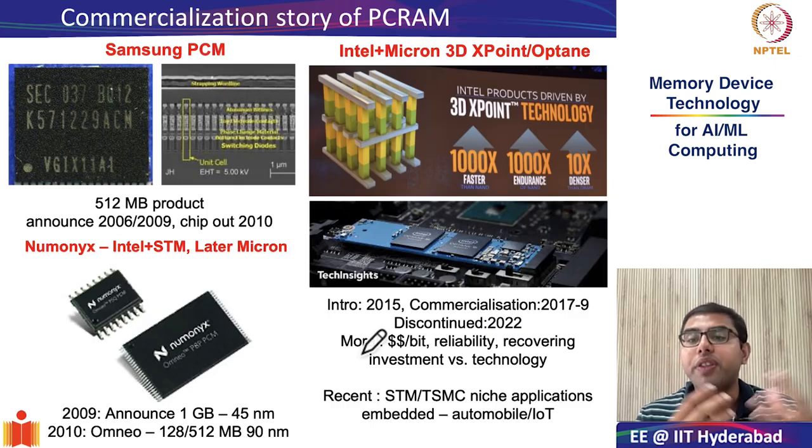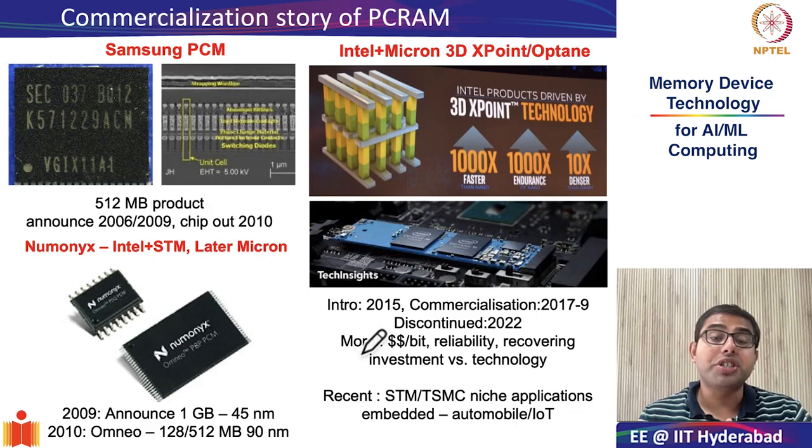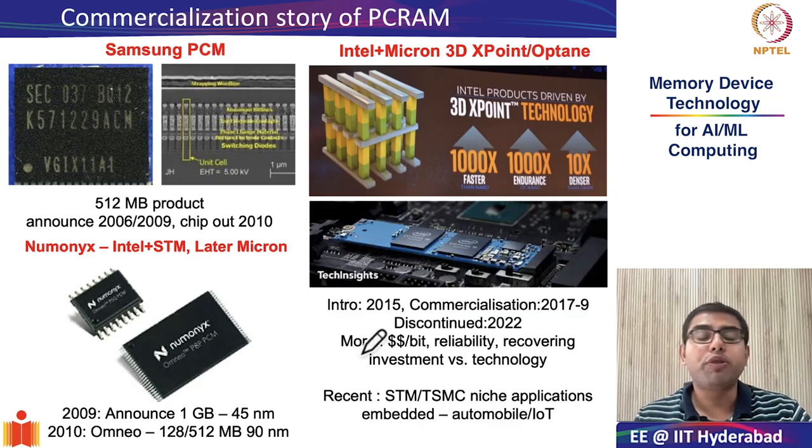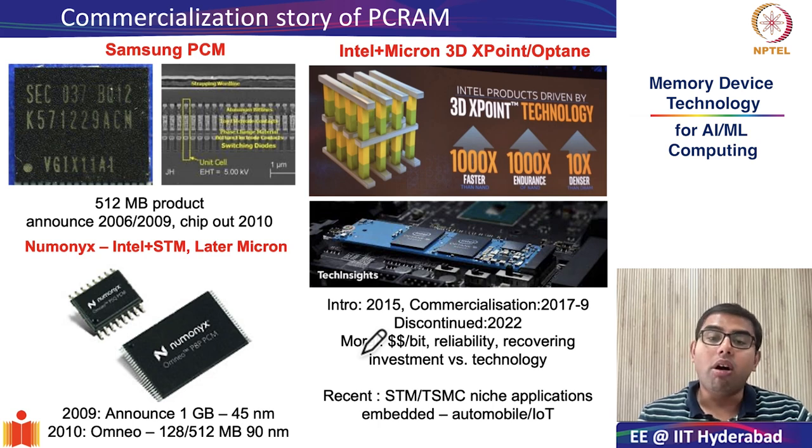They were of thermal crosstalk and having an access transistor which can supply the large reset currents which are necessary to change the device from low resistance state to high resistance state. And therefore the access transistor also needs to be very big, and this is what limits the scalability of PC RAMs to roughly 20 to 40 F squared.